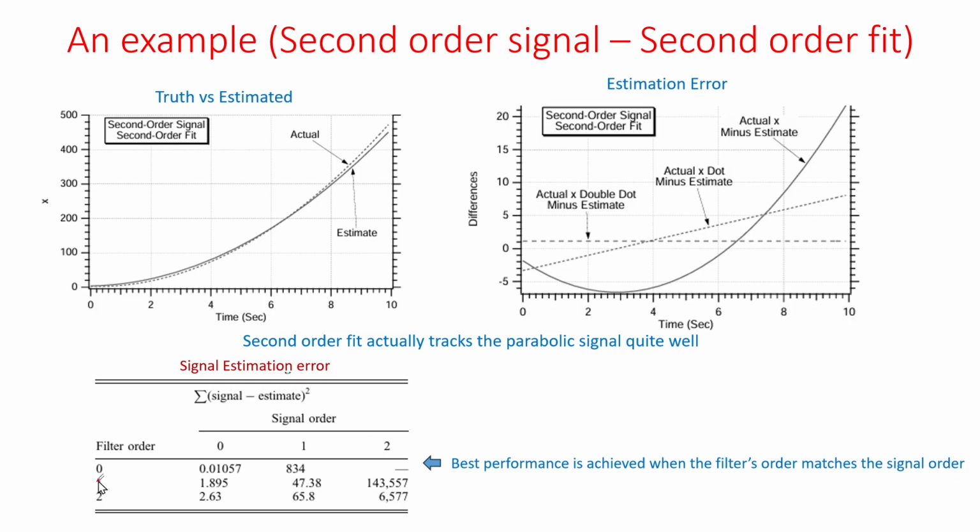Next, for a 0th order constant signal, if you wanted to do a linearly increasing position-velocity function, a straight line function, you get this much error. Do the same position function for a first order fit, okay, you get something good, but for a second order signal you are totally dead. Similarly for second order also. So, if your signal order is matching your model order, you get the bare minimum error.